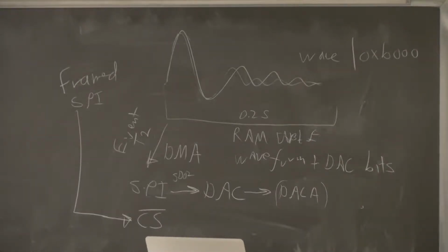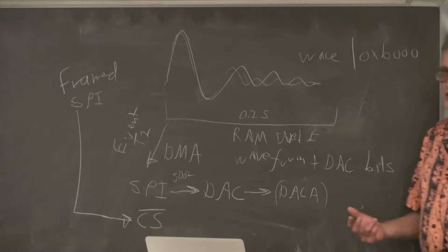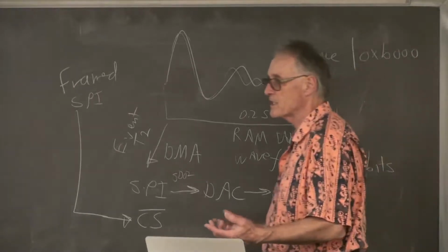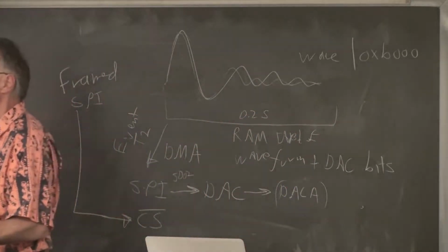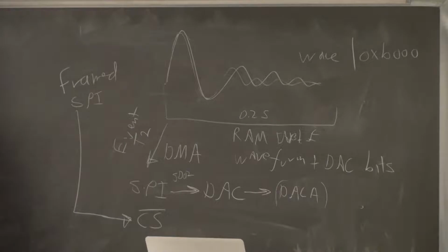And you remember how to do that? I mentioned it just once in lecture. If you use the keyword const short, C-O-N-S-T short, then the compiler recognizes that the program will never change it, cannot change it, and puts it in flash.